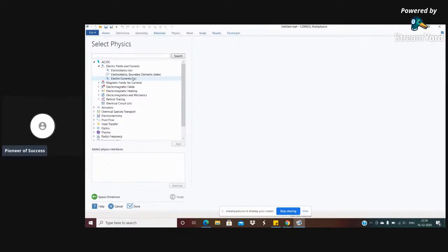Today I'll be taking a few examples in order to make you aware of how to use COMSOL for your physical problems. But before going into a particular physical problem, let me show you a few more options. Like we have acoustics. People who are working with acoustics may use these modules. The available modules are simple pressure acoustics, aeroacoustics, and thermoviscous acoustics. So it depends on which area you are working on. You choose your module, go to the module, see the equations, match the equations with the differential equations which you intend to solve, then decide upon the module to be used.